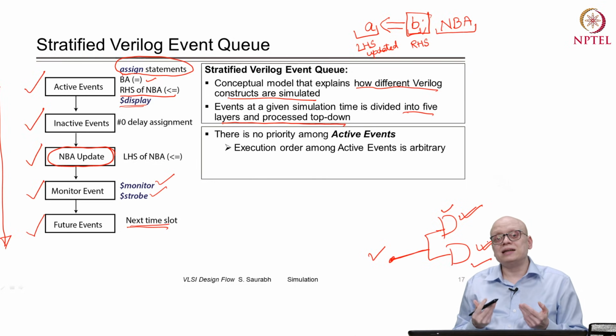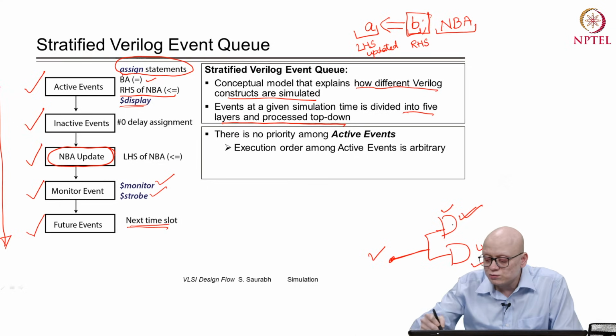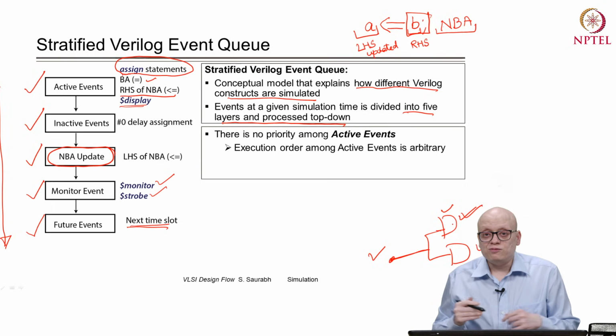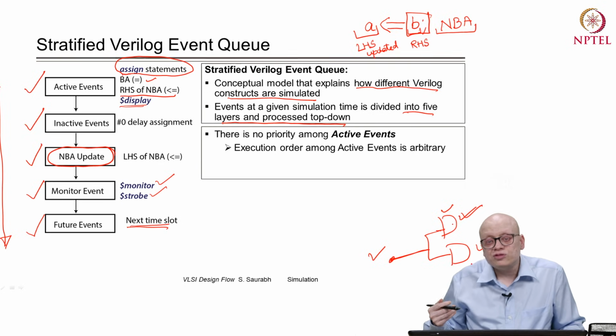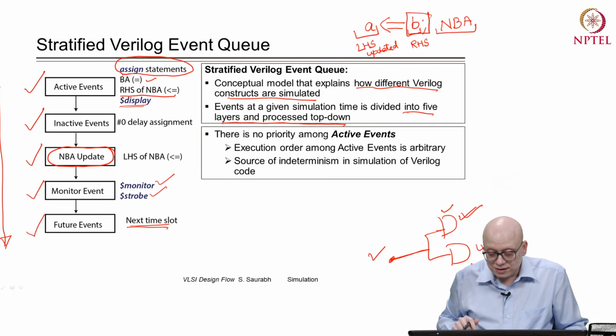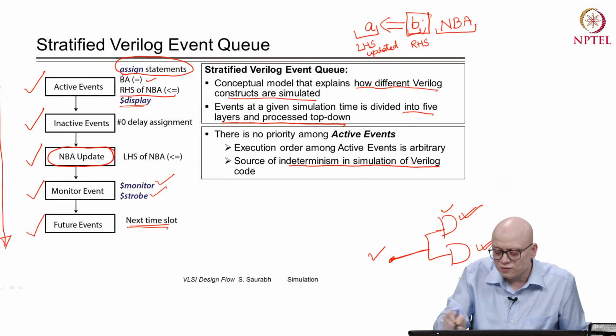Ideally, our functionality shouldn't depend on which one is processed first, and therefore the tool or the simulator is free to process any of them. So, this is a source of indeterminism in simulation of Verilog code.